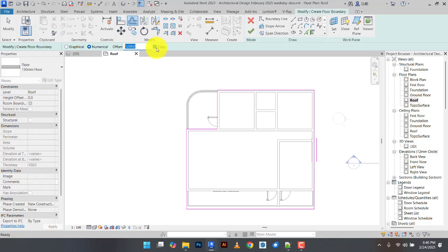Then make sure copy is on. Okay. Then now I'll come to the line I want to offset. I want to offset in. So I'll do this. Then you may want to press tab. So a tab will just select all the lines for you. Then you just click once, then offset all inside. But this time, if you click tab, this will open. It will not work.